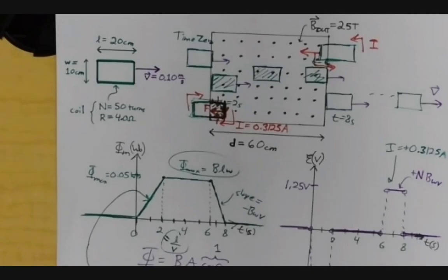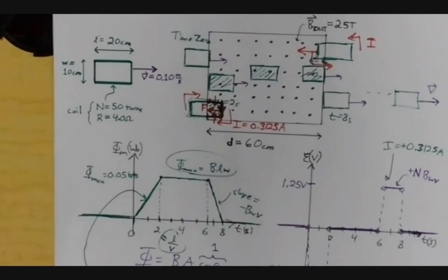Because you get some big currents induced in the piece of metal, and it's a pretty good conductor, but if you get enough current and sit it there for a long enough time, you're dumping energy into the current, and the electrons are crashing into the atoms of the object that they're traveling through, and that gets handed off to heat, eventually.